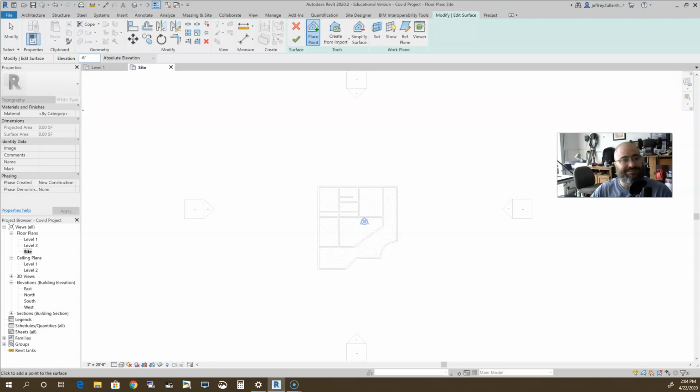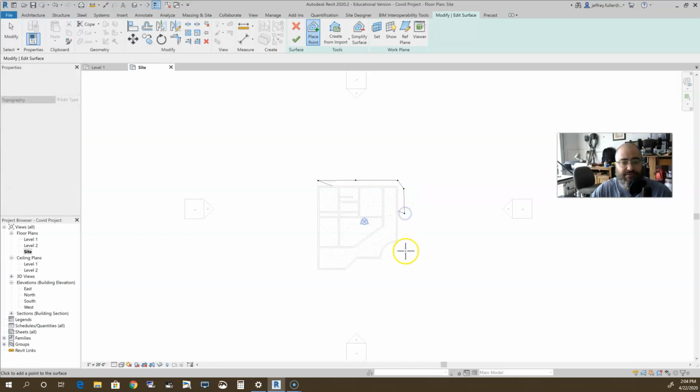Now, of course, on your test, I have no idea how they're going to ask you to do this, but everything I'm showing you will be used in order to pass that question or set of questions on the test. So I've got it set for -6 inches, and I'm going to place that pretty much right around, very near my structure. 3 dots across the back are good. 3 dots down the side will be sufficient, and maybe a 4th one.